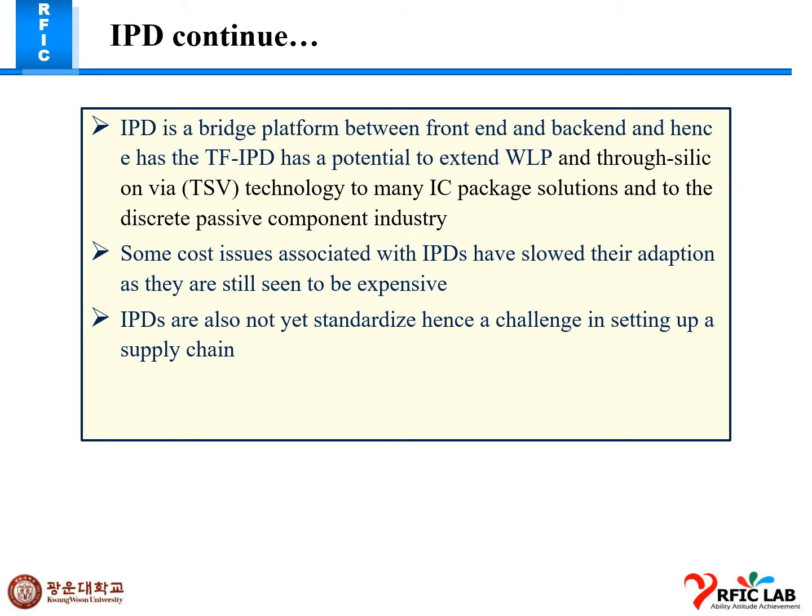IPD is a bridge platform between the front end and the back end of the models, and hence the thin film IPD has the potential to extend wafer level package and the through silicon via or TSV technology to many integrated circuit package solutions and the discrete passive component industry.